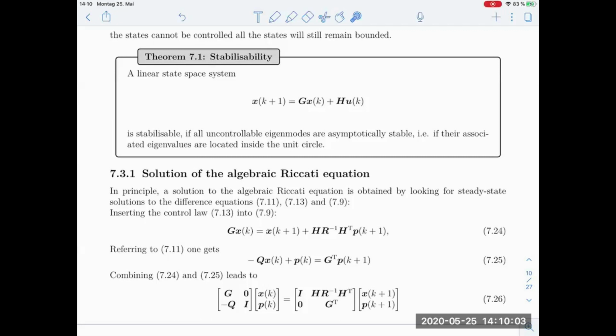That is essentially done by MATLAB nowadays. There are good and various approaches of how to solve algebraic Riccati equations. And maybe to give you some feeling of why it is important to worry about all this structure at all. Why not just minimize some optimization problem with some costs in it, and as a result you get the first U, and that's your optimal controller. The point is that if you do not use this structure properly, you will get extremely inefficient optimization problems in which you don't even know whether you are at the global optimum. And it takes just forever to compute these optimization problems.